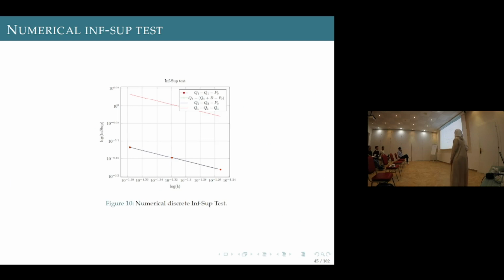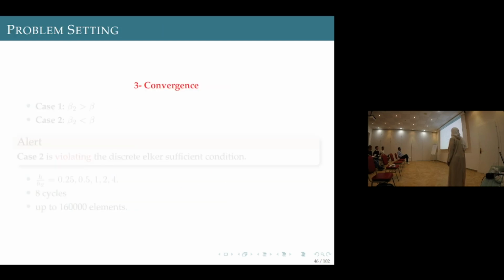And we showed that all, here I'm showing also some old work, which is Q1, Q1, Q1, but all of them, under increasing refinement of the mesh, are bounded away from 0, therefore all of them pass the inf-sup test, including the one that we didn't show, which is Q1, Q1, P0.